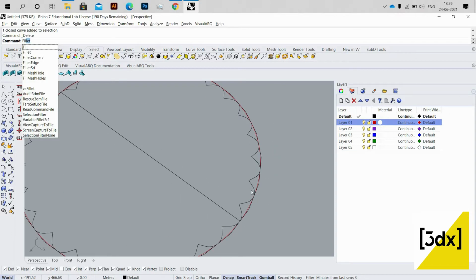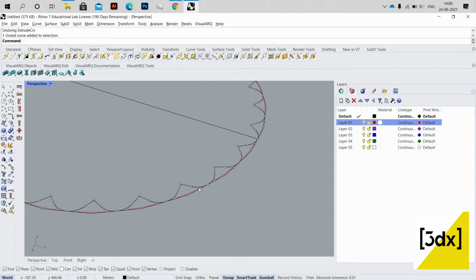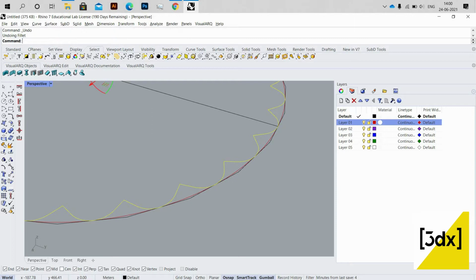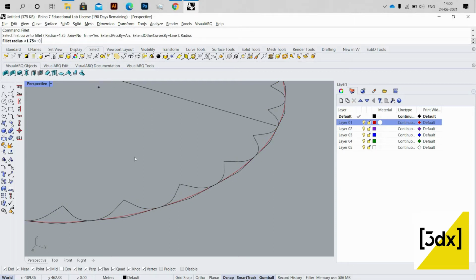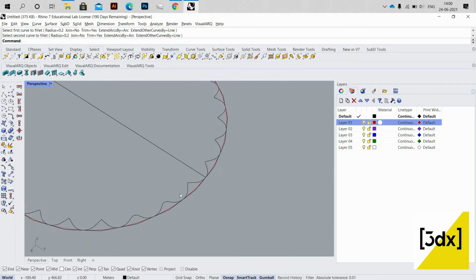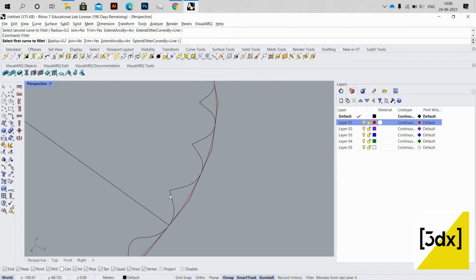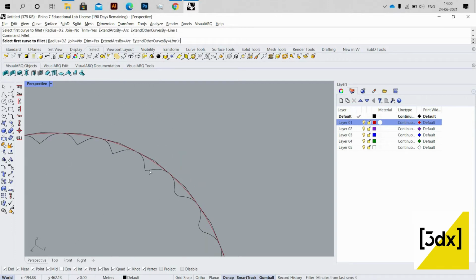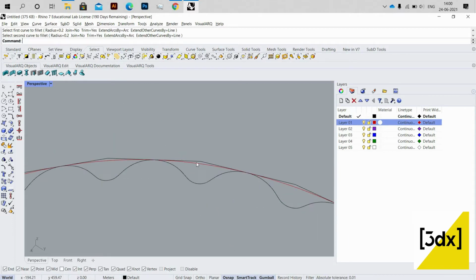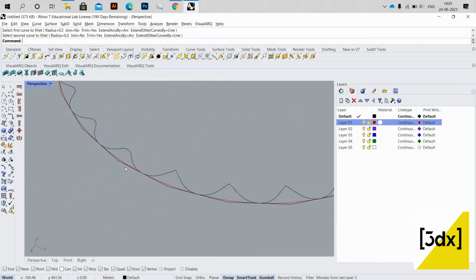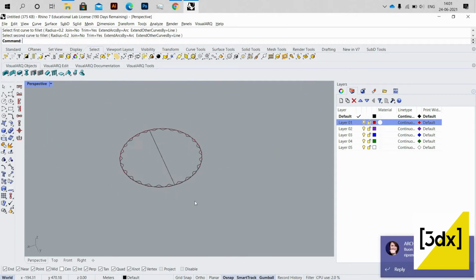But I don't need these corner edges, so I'm going to use the fillet command. I'm using the fillet command right now, but I definitely need to change the value, so I'm just changing the value. This is fine. So I'm doing it to the entire 26 edges. Now the fillet has been done.